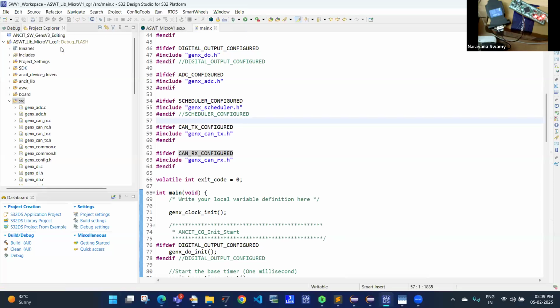So now this is the NXP S32K144 series microcontroller, which is an automotive grade ASIL B certified IC, which is used by most of the automotive designs. And this is ASIL B only. Some of the cases where you need ASIL D, NXP has their own controllers like 344 and other series. In this board, whatever board we are promoting, this is the board which we have developed. And this contains the NXP S32K144 series.